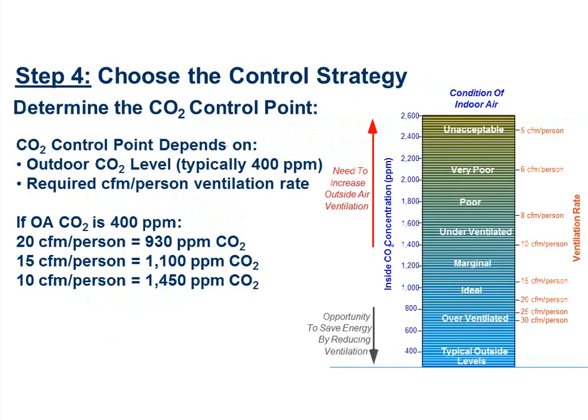Move along here and skip a little bit ahead. The kind of set points that I want are depending on the activity level in there. Like I said, for a typical office building, it ends up being a differential between outside and inside of 700 parts per million. Normally, you're going to probably register about 450 parts per million here in the Midwest. That means my indoor set point is 1150, right? That's kind of how that works. And this chart over here just gives you a little bit of a scale on what's good and what's bad if you walk into a building with a handheld meter, right?